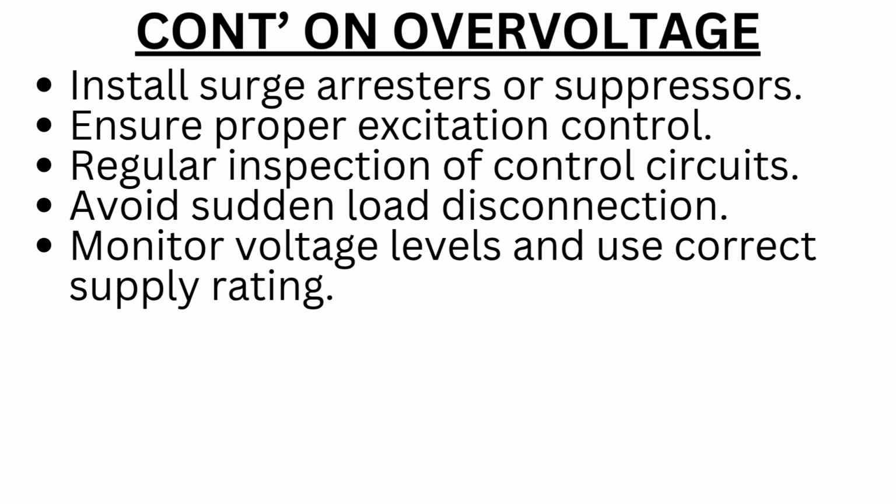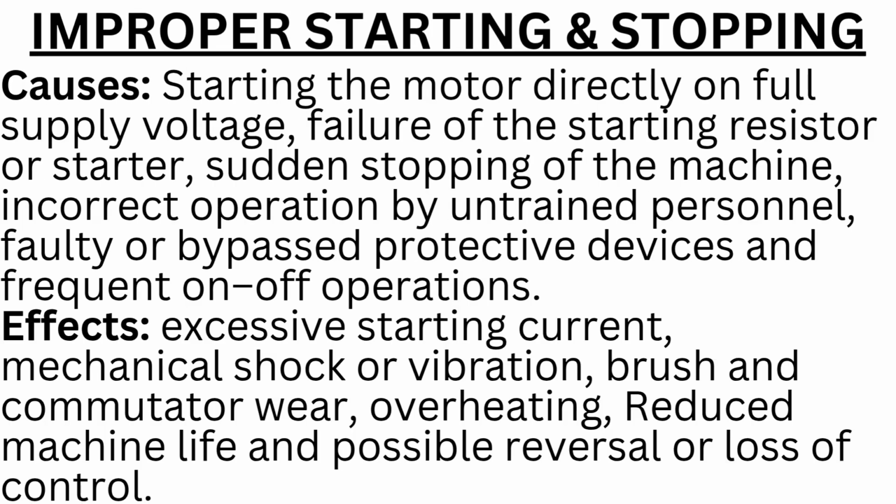Install surge arresters or suppressors. Ensure proper excitation control. Regular inspection of control circuits. Avoid sudden load disconnection. Monitor voltage levels and use correct supply rating. Now let us look at the next operational failure, that is improper starting and stopping.